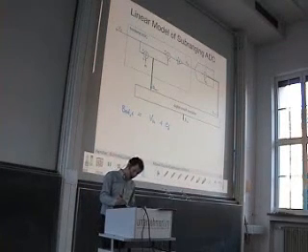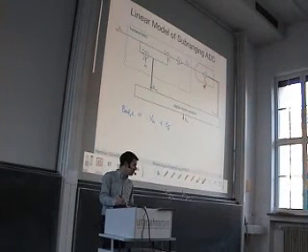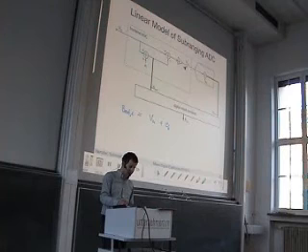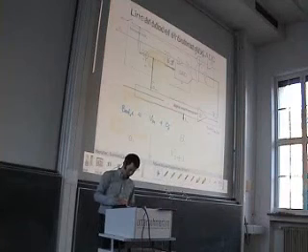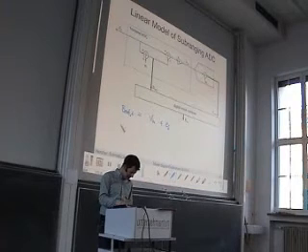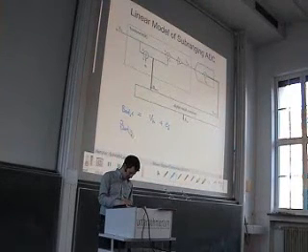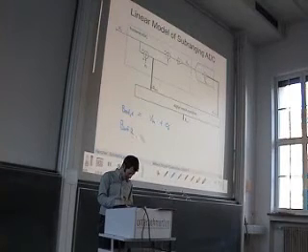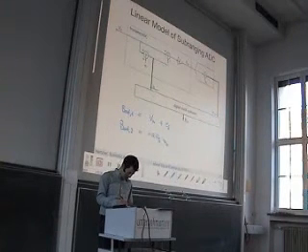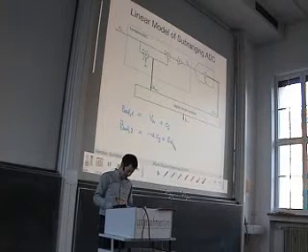The back end ADC adds a quantization error EB, and the input signal of the back end ADC is the output of the front end ADC, and we have seen on the previous slide that this is A times the quantization error that we have here. So I use the second formula, which is B out 2 equal to minus A EF plus EB.